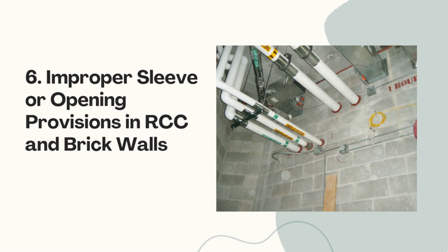How to fix this? Make sure MEP contractors give sleeve or opening requirements for both RCC and brickwork to civil teams during the shuttering and blockwork stages. Use sleeve drawings and embedment plans for the execution teams at the site level.